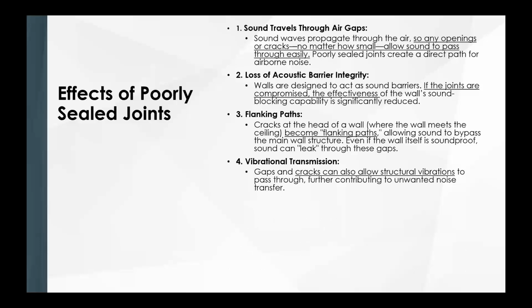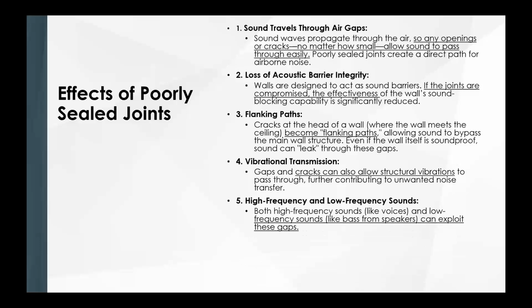Vibrational cracks, okay, that could happen too. Sometimes the walls are tall. You could have some structural vibrations, which could cause some cracks and unwanted noise transfer to get through. High frequency, low frequency, like voices, that could go through from one side to the other. What's the solution? Permanently flexible joint protection.